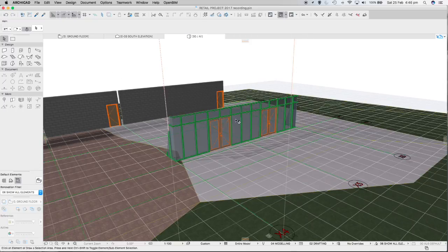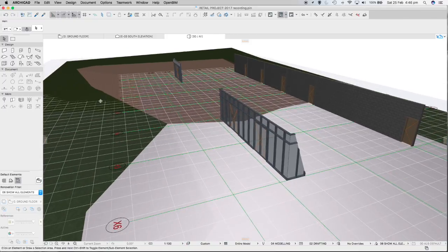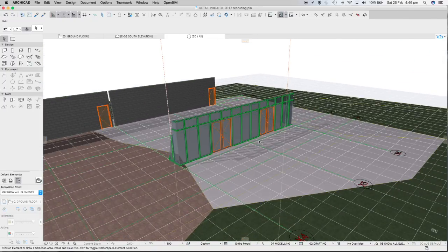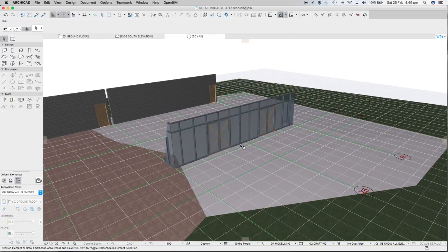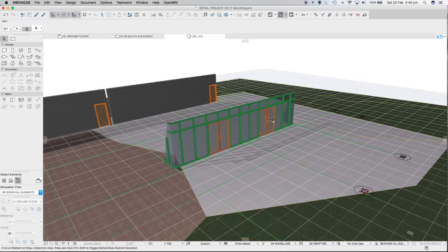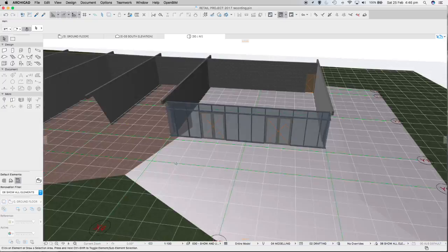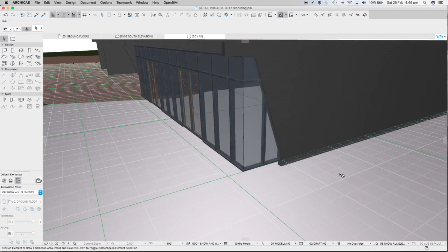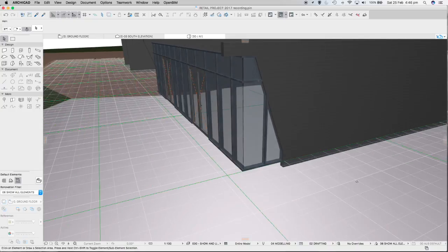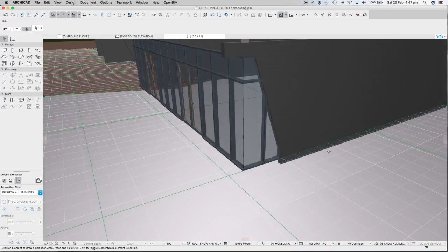Okay, so then we can click, if you haven't already, click OK to that curtain wall editing dialog box. I think I must have hit the escape key, which let me get out of it without pressing OK or something like that. And we can then view guideline options, remove all guidelines, and that tidies up all the guidelines. And then if I go back to the layer settings and do something like show and unlock all, it turns on the concrete tilt-up panels. As you can see, from the point of view of visualization, you hardly miss that missing frame down at that point there. The line of the glazing almost makes it look like there's a bit of framing there anyway.